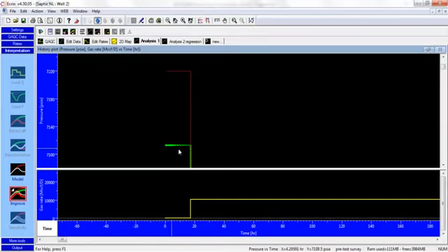This was the pressure trend before starting production. You need to be cautious here because at that point in time, below the gauge, you might have some drilling or completion fluids, or the fluid weight below the gauge might be a bit different. So what you have is an estimate of initial pressure, but it might not be the exact value. But we're going to use this one as a starting point.